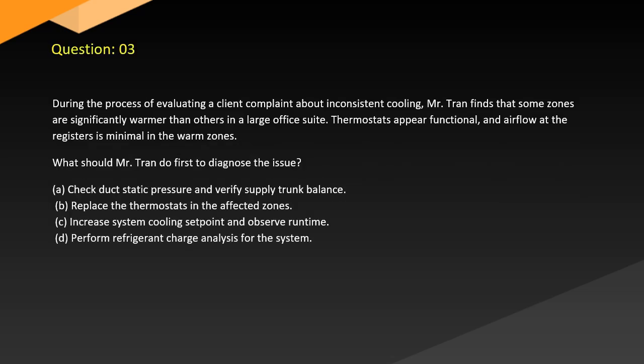Question 3. During the process of evaluating a client complaint about inconsistent cooling, Tran finds that some zones are significantly warmer than others. In a large office suite, thermostats appear functional and airflow at the registers is minimal in the warm zones. What should Tran do first to diagnose the issue?